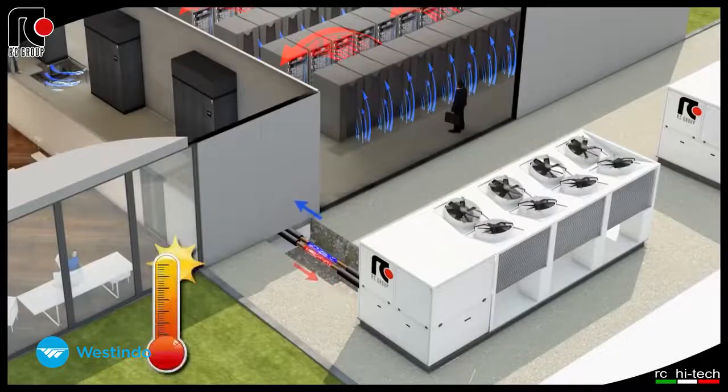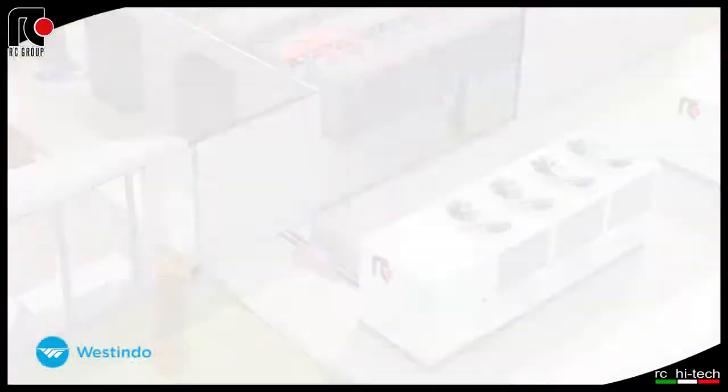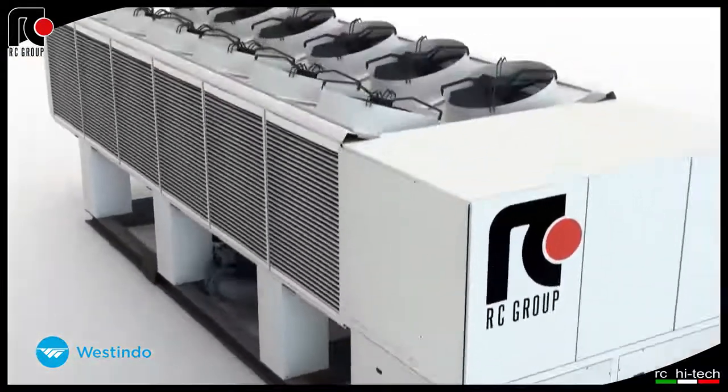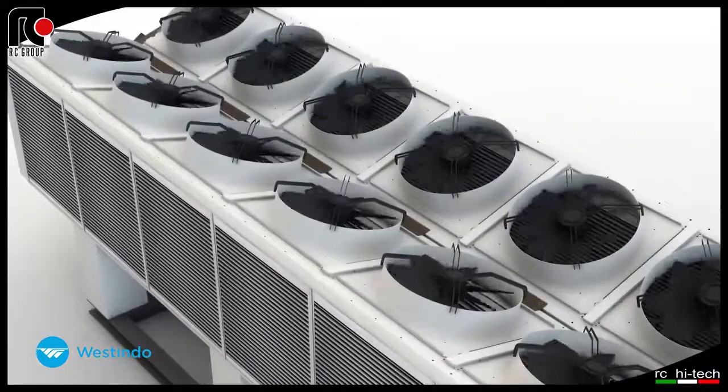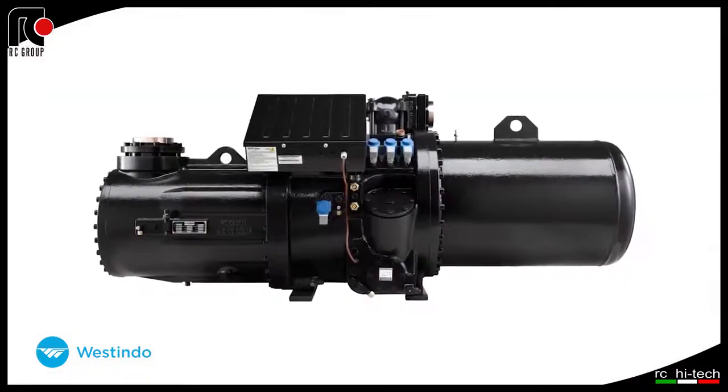When the external air temperature no longer permits full capacity free cooling, the glider-free works in a combined mode, maximizing the thermal exchange of the free cooling coil and compressors, having modulating capacity control. Main components are electronically commutated EC axial fans and screw compressors with stepless capacity control.